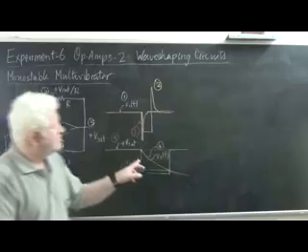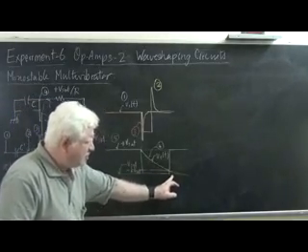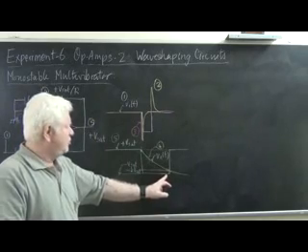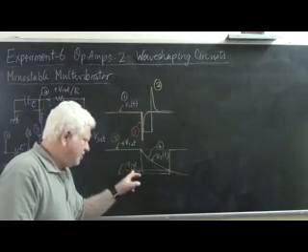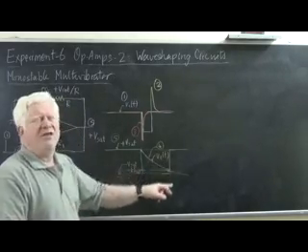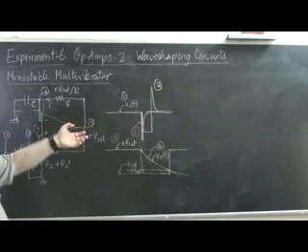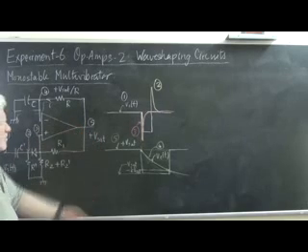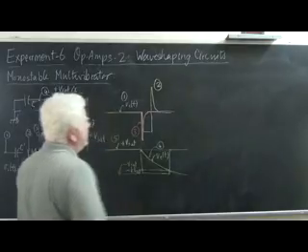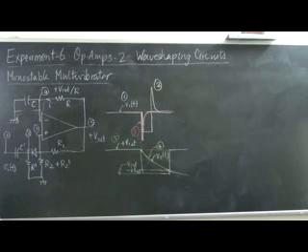So the capacitor is charging downwards towards minus Vsat, and at a certain specified point of time will cross k times minus Vsat, which is this point. And as soon as it does that, the op amp returns to its previous static state, which is plus Vsat. So the entire history of events can be summarized as follows.